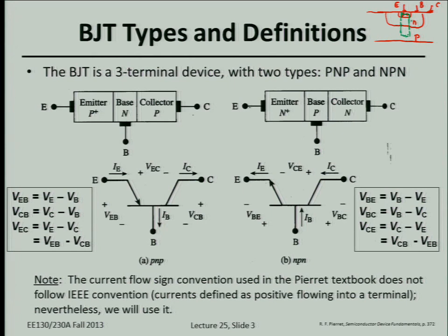So we know that to get current into and out of the base, we have to flow through this resistive, doped silicon region. And to get current to flow in and out of the collector, usually we have a heavily doped sub-collector down here. There's a heavily doped region here, and during fabrication, we have a heavily doped P-type region to the side, so we can get current flowing through this lower resistance pathway into and out of the metal contact at the top surface. So this is a cross-section of a more realistic view of a bipolar junction transistor.